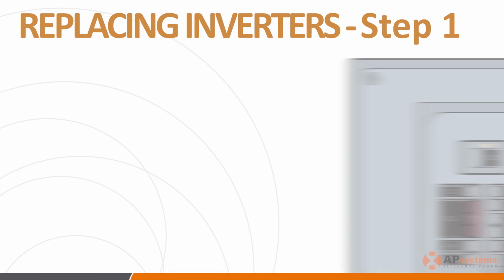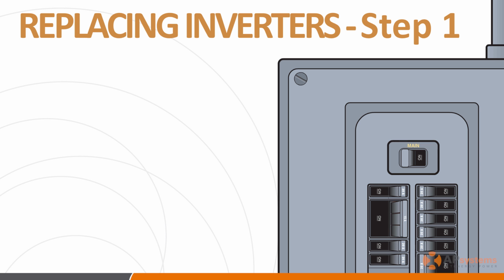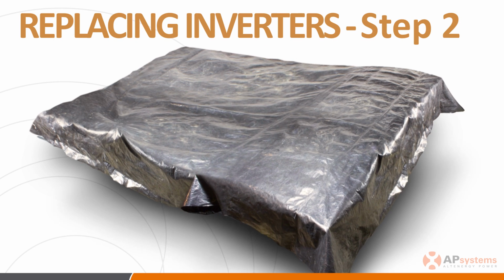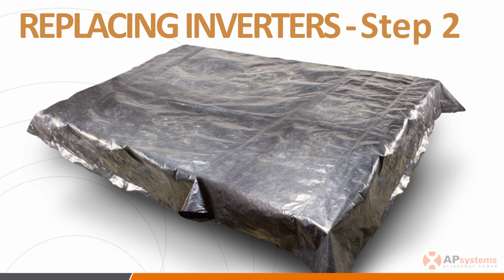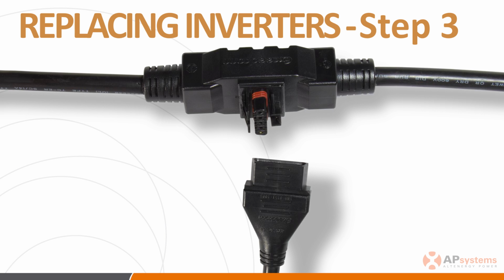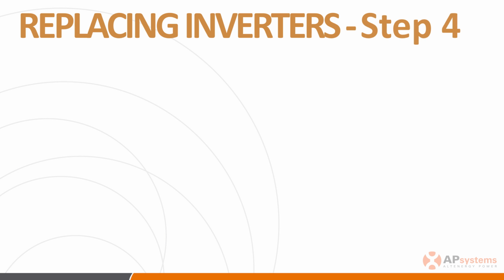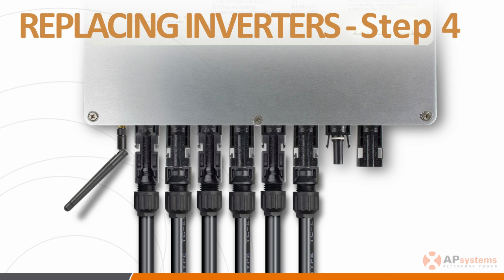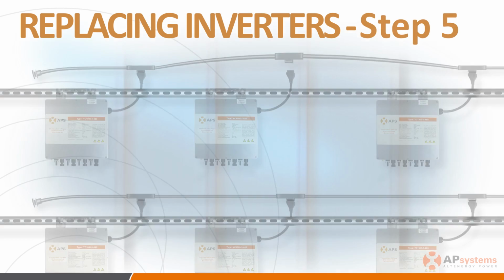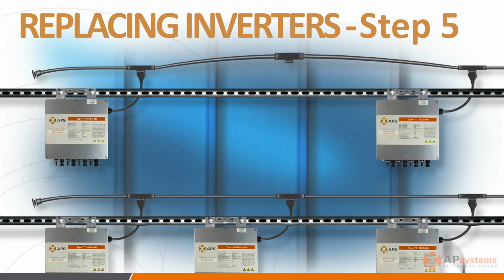Step 1. De-energize the AC branch circuit by turning off the branch circuit breaker. With the branch circuit offline, cover the PV modules associated with the inverter to be removed with opaque covers, ensuring the panels are not producing DC power. Next, disconnect the AC connectors from the AC bus cable. Step 4. Disconnect the DC connectors from the PV modules associated with the inverter. And finally, physically remove the inverter from the rack.